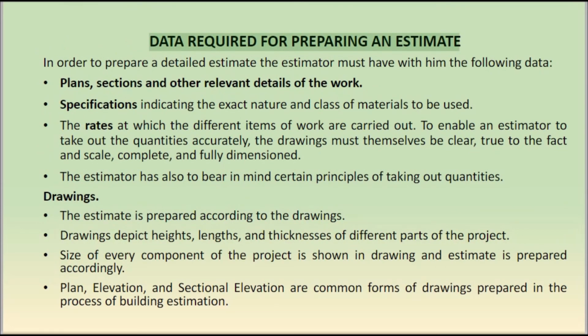Data required for preparing an estimate. In order to prepare a detailed estimate, the estimator must have with him the following data: plans, sections, and other relevant details of the work; specifications indicating the exact nature and class of materials to be used; and the rates at which the different items of work are carried out.